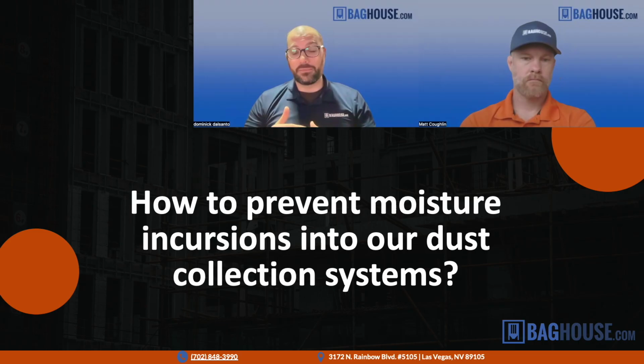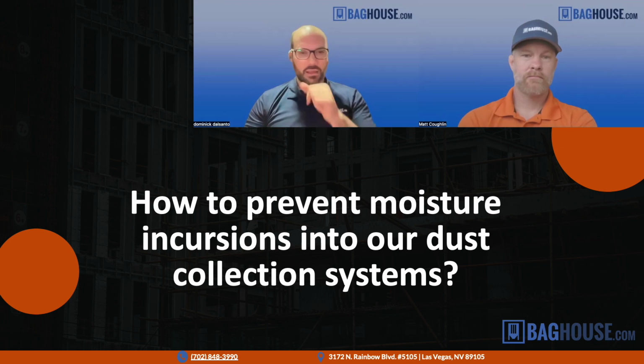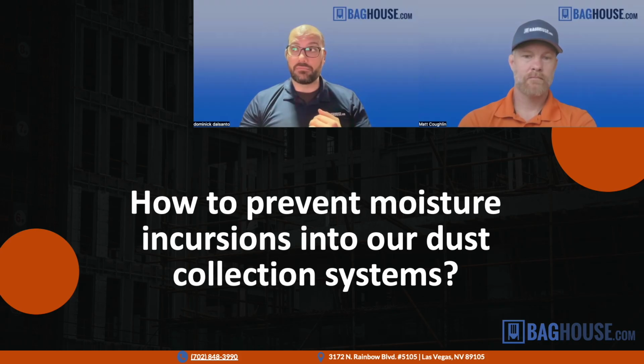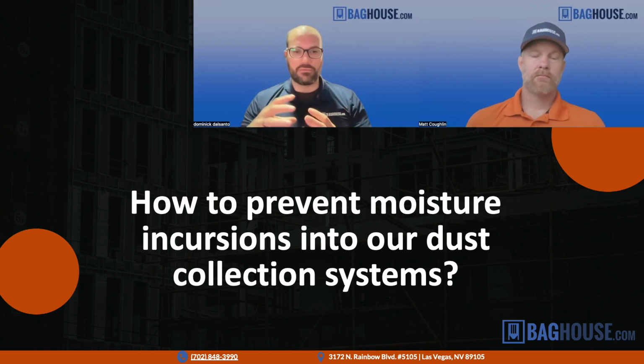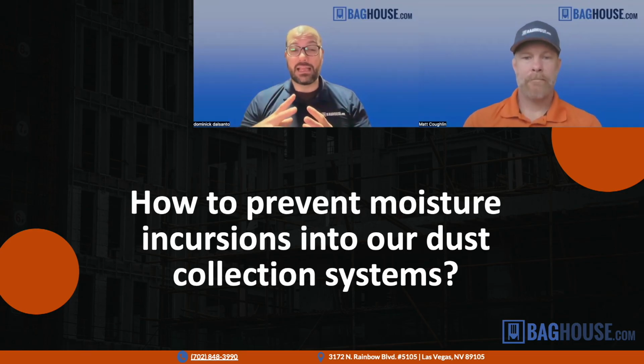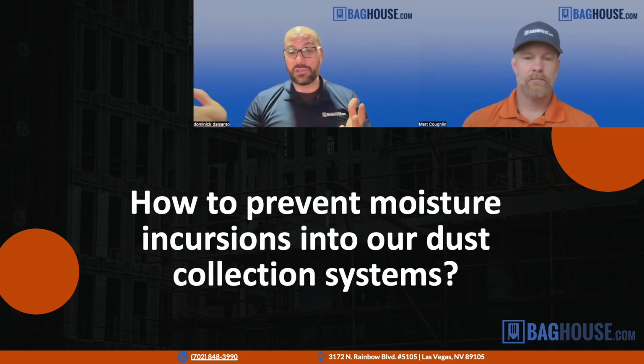Most of the time we want to keep the temperature lower, but when you have moisture, you want to keep everything warm. So from the ductwork all the way through to the baghouse and even the exhaust in the baghouse, you might want to insulate. And then many times we even have to add extra heaters like heat tracing or even natural gas heaters sometimes, but that's much rarer. Usually it's heating pads, heat tracing, things like that. And we might even modify the process a little bit so that we run at a higher temperature. Sometimes we adjust how far the hood is away from a furnace or something like that so that it sucks in less ambient air so that the gas that is going through is hotter.